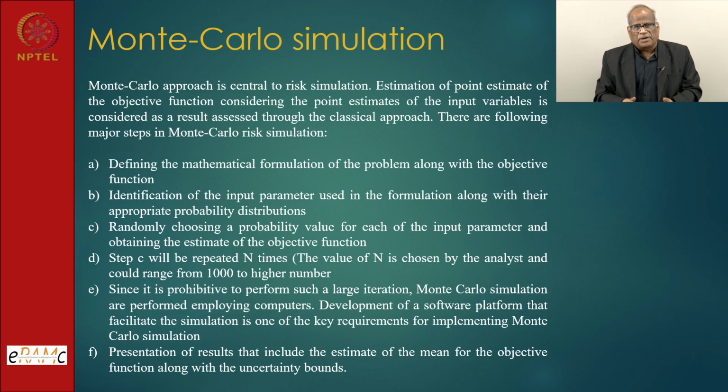So that means fault tree reduction and Monte Carlo simulation should go on together. What is Monte Carlo simulation? It defines a distribution for each component. For each component we'll provide the median value, because components coming from different sources are assumed to follow a log normal distribution. So for a log normal distribution, the median value has to be given and the distribution has to be given.